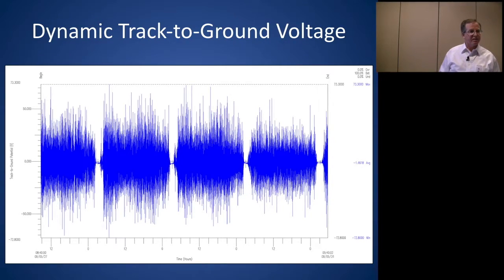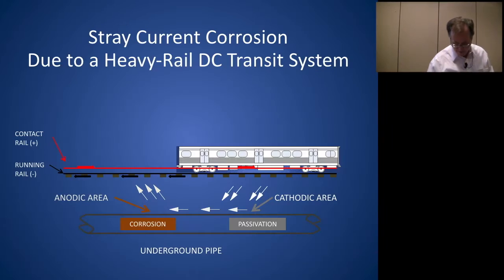What magnitude current will it be? Well, for a traction power substation, the amount of current that's traveling those rails and returning to the substation depends on the system, but it can be anywhere from like 6,000 to 8,000 amps. Well, I'm thinking about the magnitude of this stray current. So at 50 volts, what current level would that be to personnel? Well, we'll get to that.